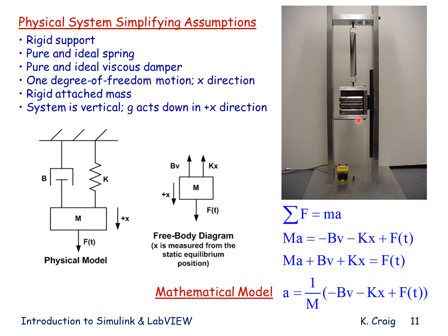The next step is to draw a free body diagram of my mass. So I simply take this mass and I take it out of its environment and I draw it on my page. I will show all the forces acting on this mass. The forces that are possible are forces that act at a distance, electromagnetic forces, and gravity, weight, and forces of contact. No contact, no force. I have no electromagnetic forces. I do have weight. However, as we will see, I need to specify where I measure x from, and I have two choices.